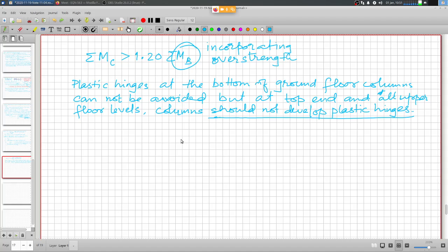If you look at IS 13920, the special ductile detailing provision, this closed spacing, the confining steel is not only for the beams, even in the columns you have to provide this ductile detailing, right?